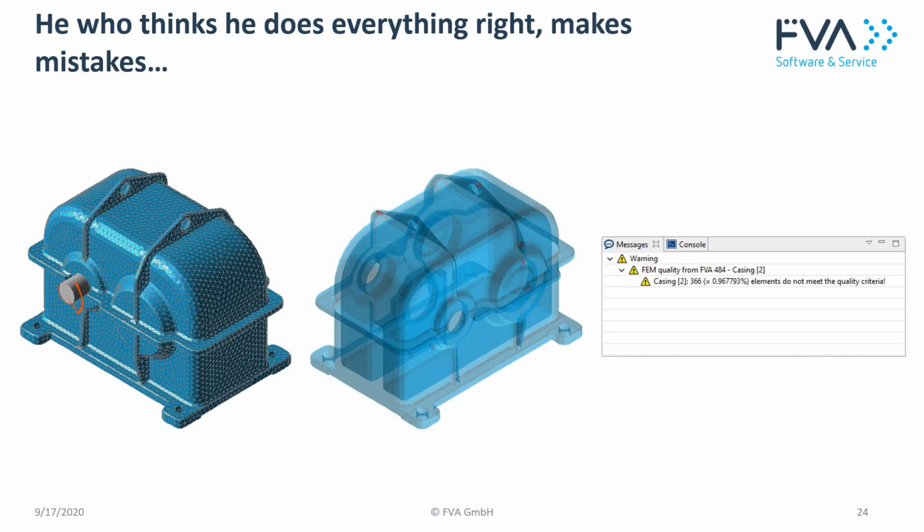We'll move on to a word about meshing quality. So information that was available from the recent feature for calculation of FE wheel bodies included what percentage of elements do not meet quality criteria, which can lead to meshing problems for casings, planet carriers, etc. So we've now included that in the Workbench as a warning message, which can be very helpful for evaluating the meshing quality. So for example, what we see on this slide looks good. However, as we can see from the warning message, the meshing quality is actually not sufficient, which can lead to distorted elements.